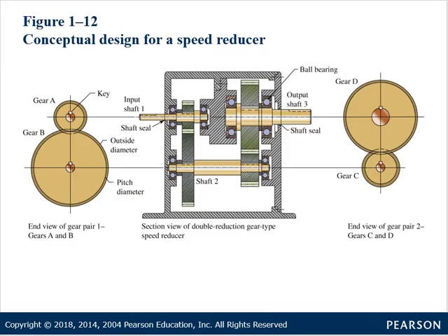This talks about a speed reducer, okay? So in which case we have shafts. These shafts will transmit torque. We have bearings here that remove some of the friction. And then here we have gears. Now, when we start talking about Chapter 8, Chapter 9, we're going to talk about the loads that are imparted on gears by just the very turning of the shaft, or the transmission of torque actually causes loads on the bearings. And those bearings go into the housing. So all these loads will act together.